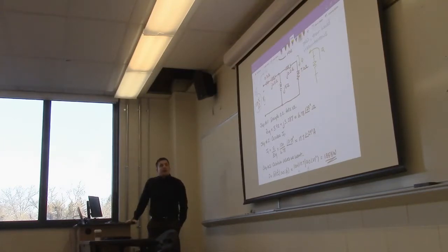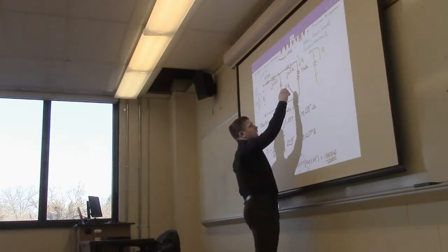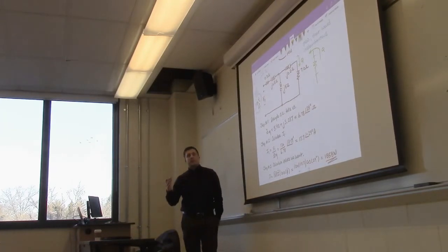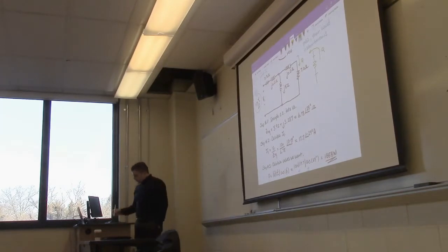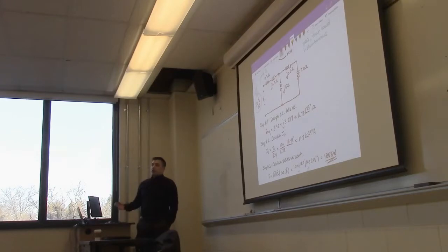Which means that, from the point of view of right here, when you're looking at the load or scoping the load, looping the power factor correction element in with the load, the power factor will be 1. In essence, placing a series element wouldn't allow us to inject or consume reactive power directly from the node, like how we need to do it.